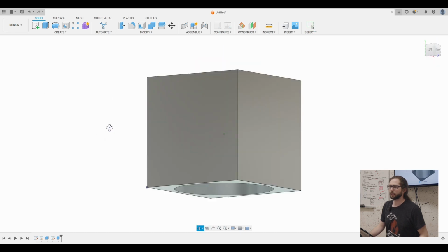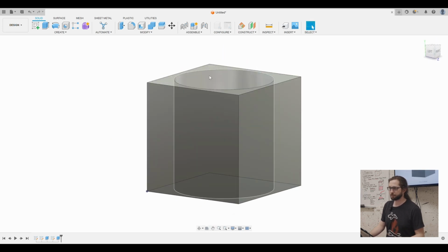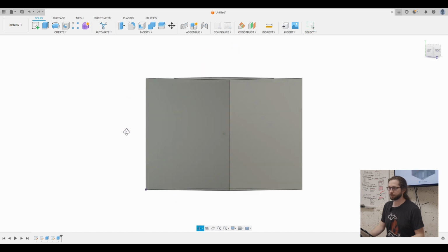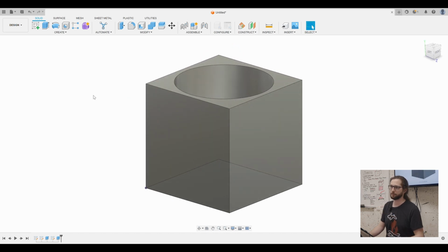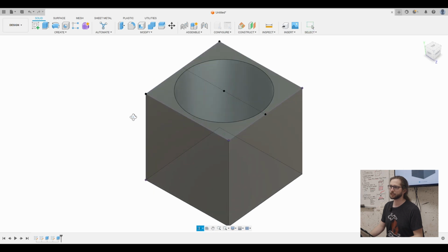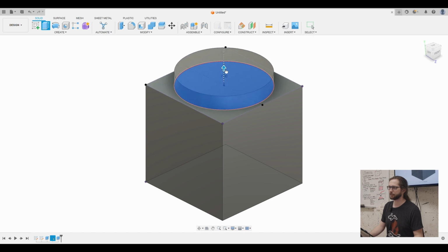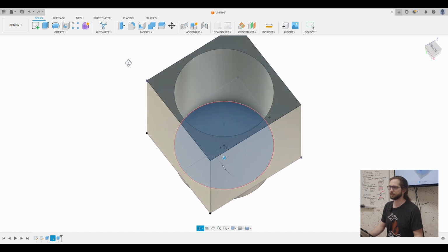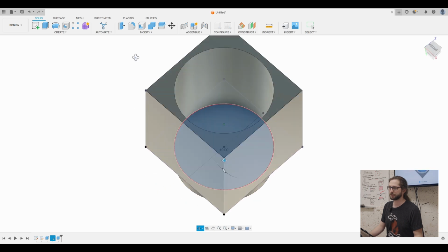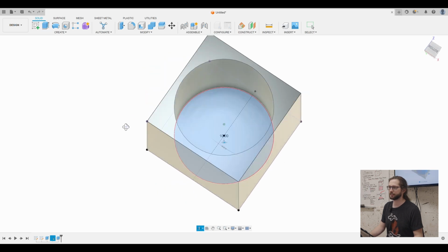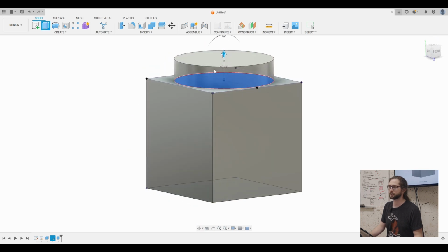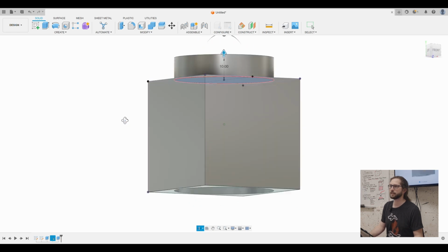Probably more important. Yeah, so notice that Fusion, again, by default, hides the sketch that you use with the transform tools. But just to your example, I want to bring it back just to show you that you could, if you wanted to, now use extrude again on that sketch and then make something else, right? This wouldn't be printable because this doesn't connect, right? Like this is a weird edge right here. But you could do that if you wanted to.